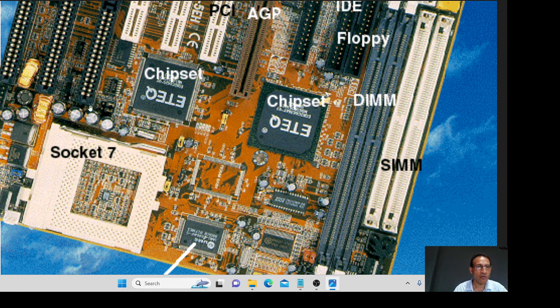So that electromagnetic interference might affect the data. The data means zeros and ones, plus voltage and zero voltage. Then it might change a 0 to 1 or a 1 to 0. It might have a huge effect on the data stream. So this electromagnetic interference produced by the voltage is absorbed by these two coil structures.